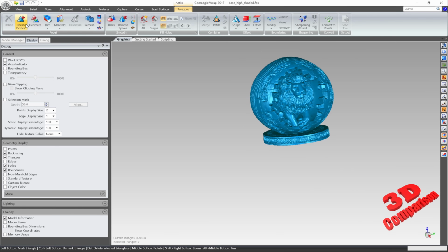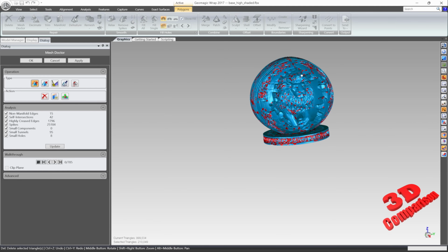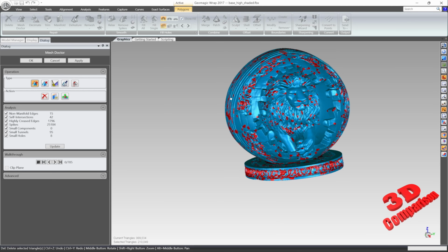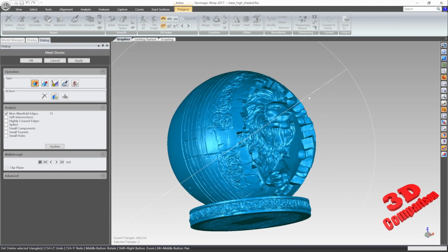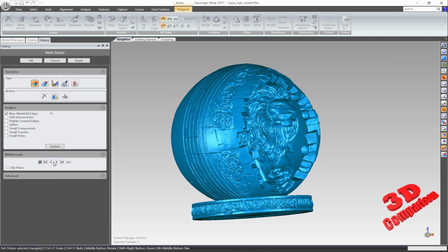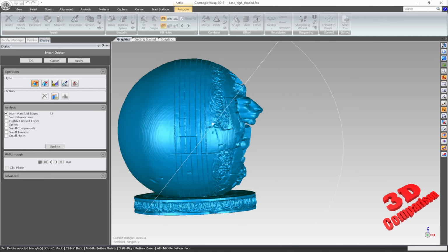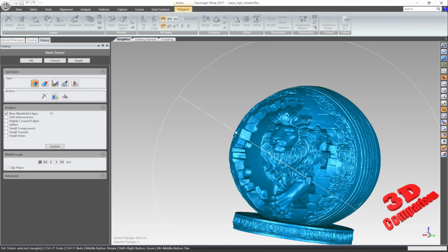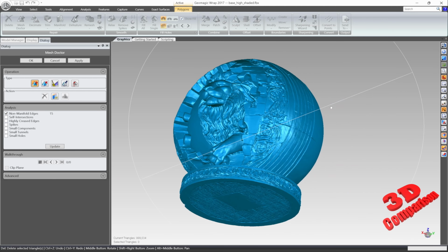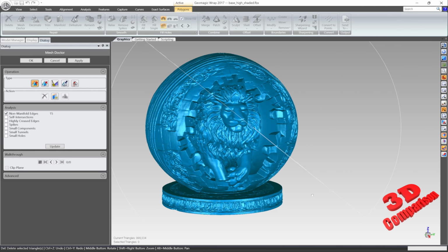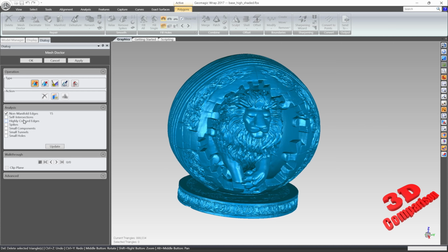And let's do that mesh analysis in order to see what kind of problems we have over here. And we're going to see that Rodin will also create some non-manifolds. I'm just going to disable everything and I will leave those so we can better see those. We have a button over here for walkthrough, and this will show us some of the elements. In this case, we're going to see that those non-manifolds will be a total of 15. I don't know exactly where they are on the mesh, but we see that the mesh will have those.